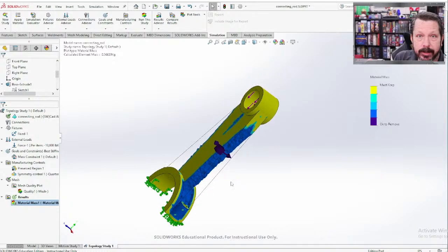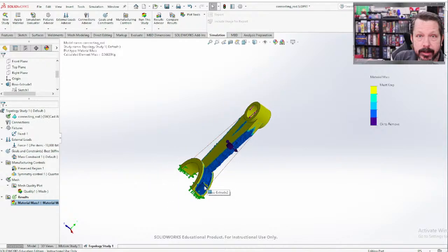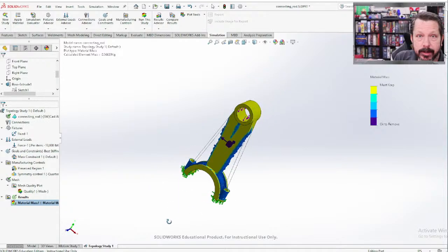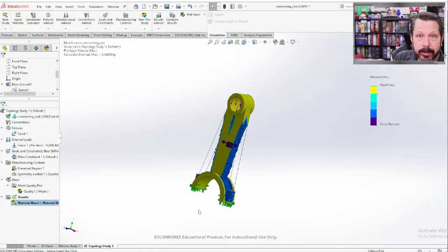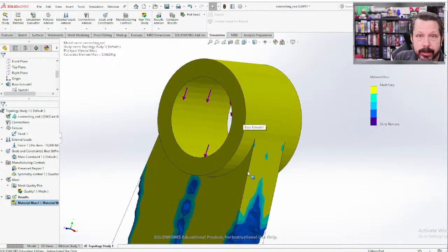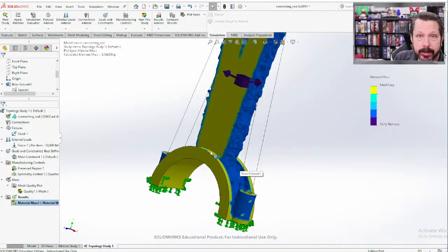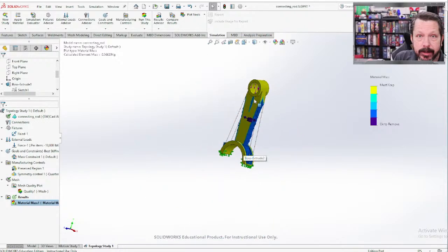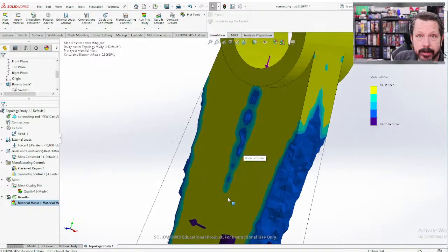There are other stresses. We did a perfectly vertical compression load, perfectly axial might be a better way to say that, an axial compressive load on this thing, and that's not quite true, but that's what we're going to work with here. So what you would do next is you could do one of two things. You could just take this and say, okay, I'm going to go design this shape, and I know I've got some things. I didn't put a fillet here and none down there. I don't really like the way this is happening. I could probably beef up this little divot. I could probably get a little more out of that.